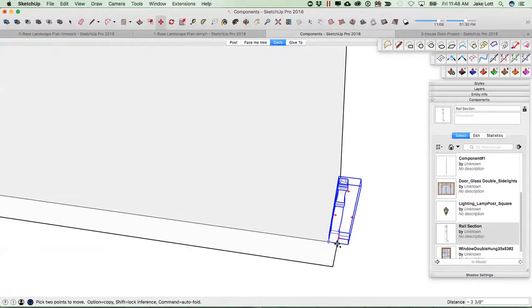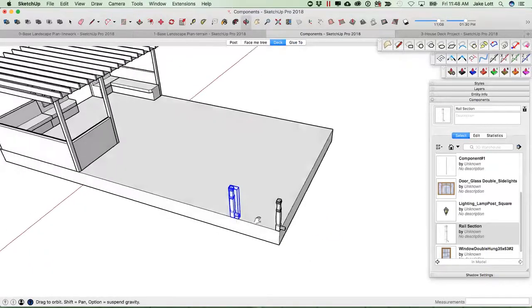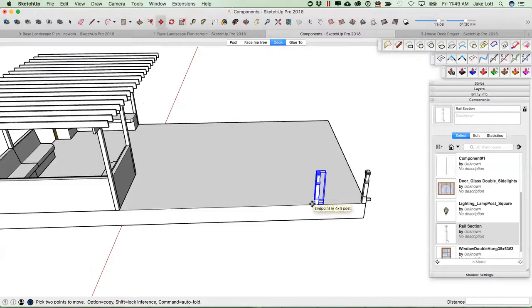We're going to make a copy of him, and we're going to show those hidden commands with the copy feature. So as I'm dragging him out this way, maybe I want them every 4 feet. So that's 4 feet apart, and we'll go ahead and say I want 4 times that. And it automatically starts putting them at 4 feet, and there's 4 of them.